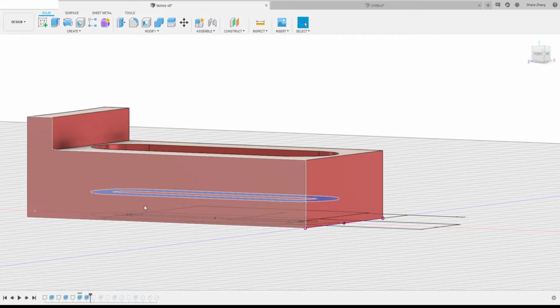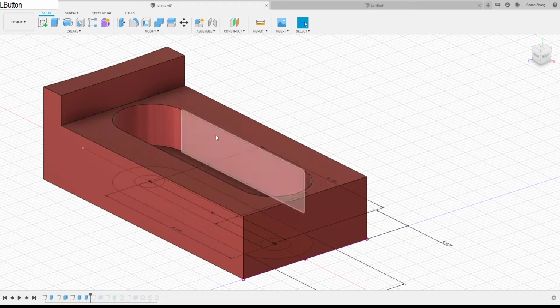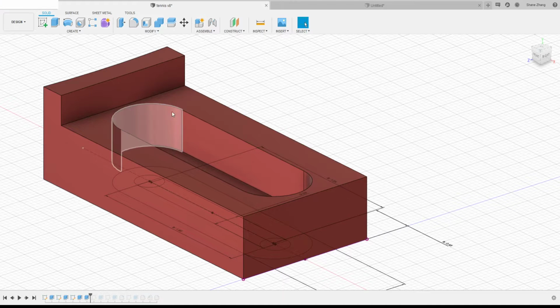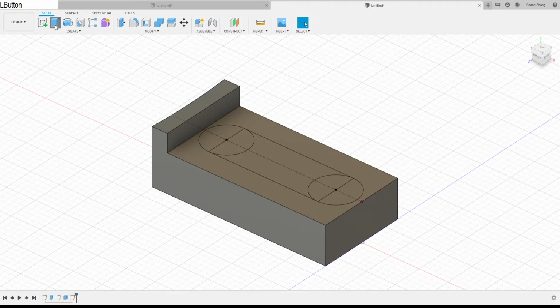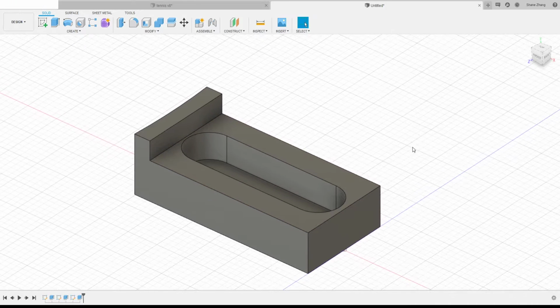As you can see, the sketch is at the bottom, then this big slot is extruded a little bit off, then upwards, but rather on the new model I would use this depth, 0.415. So when you click on a line or an edge, it'll show you the length right here at the bottom. So 0.415, we can extrude this way. It's a little bit more realistic to how the machine goes. So the machine will touch the top, or they will find a reference from the top plane and go down this distance. So it will be 0.415. Okay.